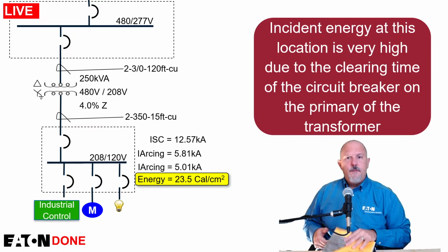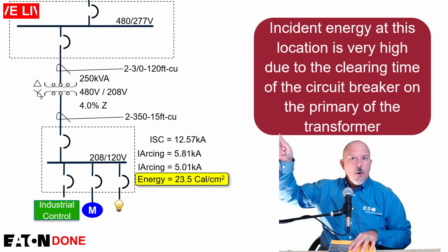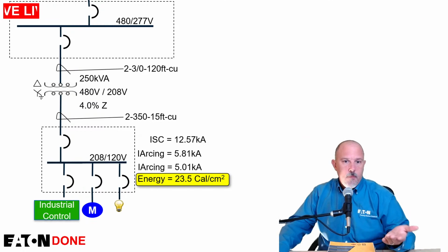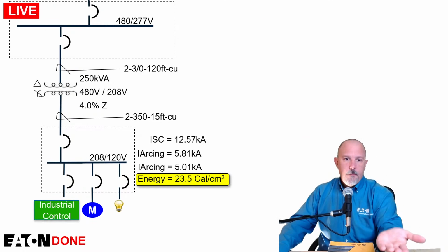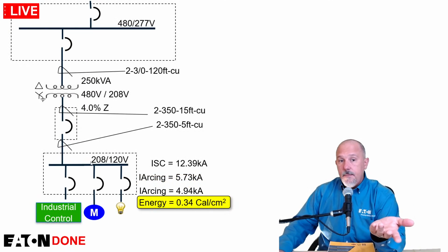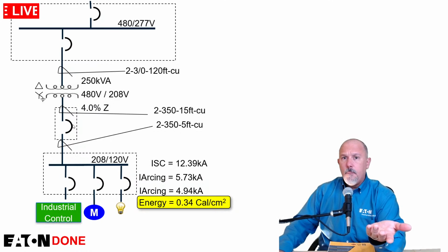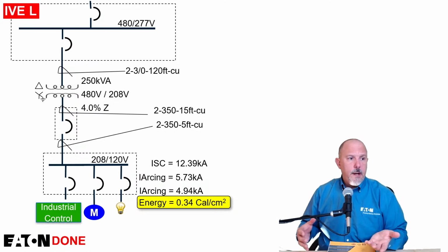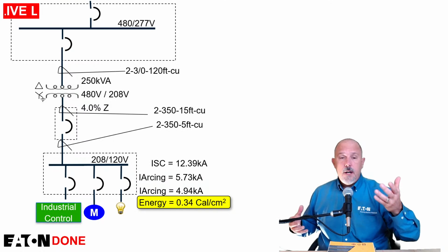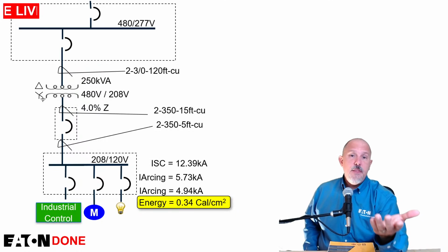If I'm following 70E, I'm going to need to go upstream to determine the table methods. So I need to know what breakers are feeding what. If, for example, my next upstream device is actually a breaker in a box, a single breaker with a disconnect, I'm going to need to know where that's at and the fact that it's there.